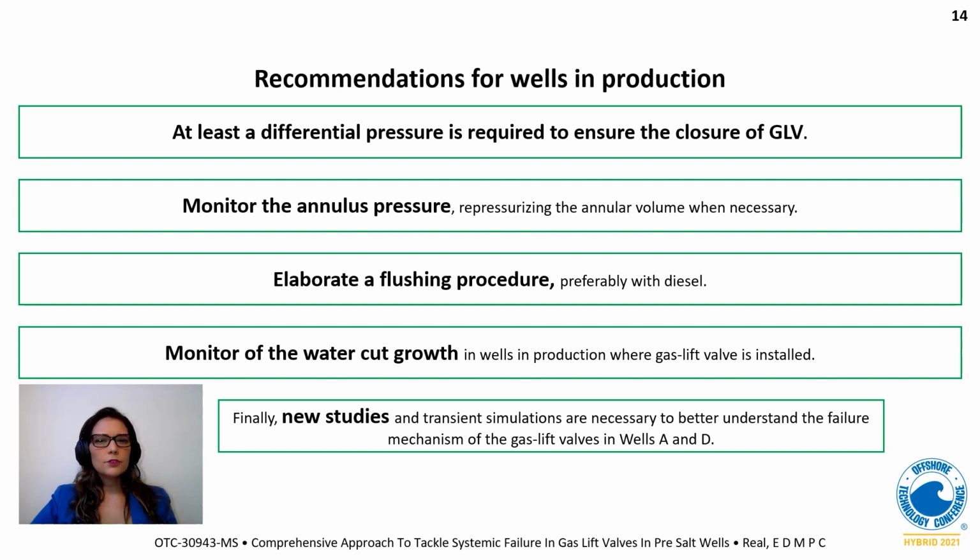If the gas lift valve is already installed, check the absolute pressure and the differential pressure that the annulus is subjected to. There is a possibility that the valve is open, making possible the contact between the annulus fluid and the produced fluid, which brings a high scale deposition risk.